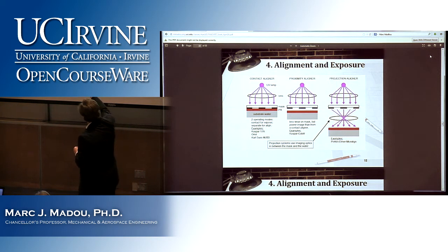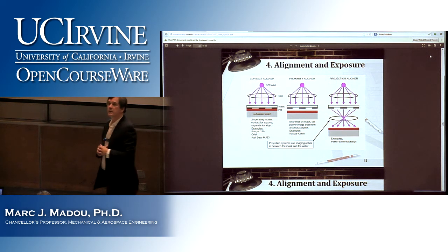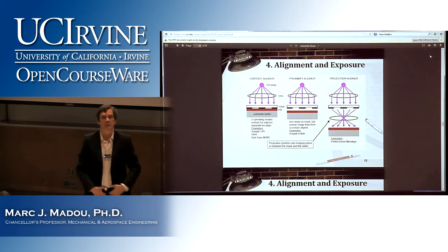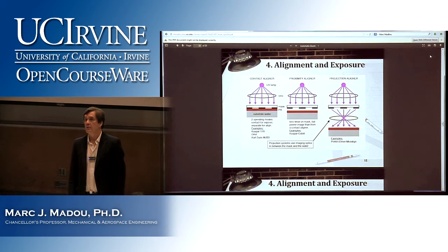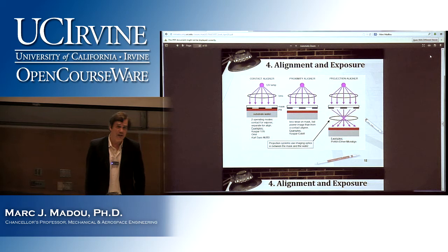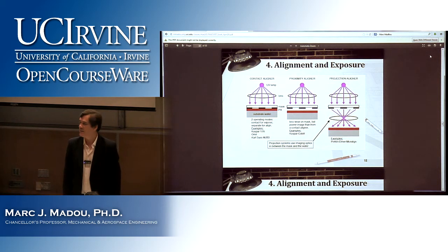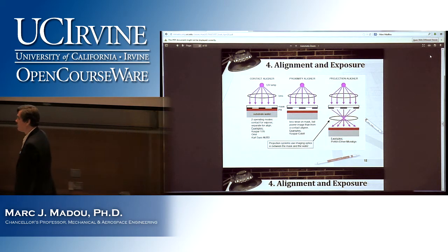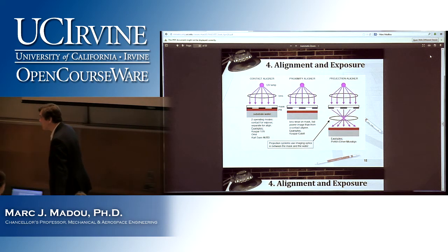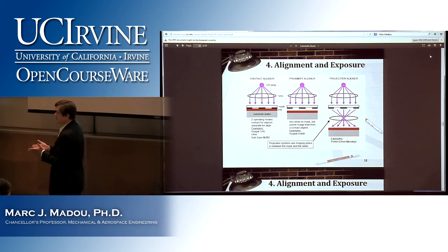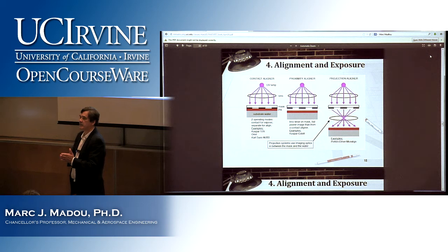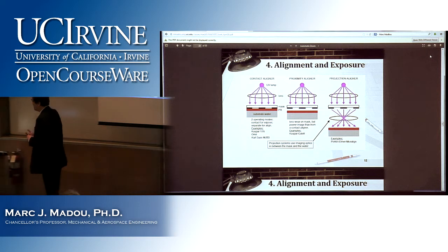So if I compare 1 and 2, which one do you think has the higher resolution? 1. But then it's not very popular to use. Why is that? Wear and tear on the mask. Exactly, because you literally have your mask sitting on your wafer, so you'll damage things. You might even have some resist that's sticky and sits onto the mask, and it's over.